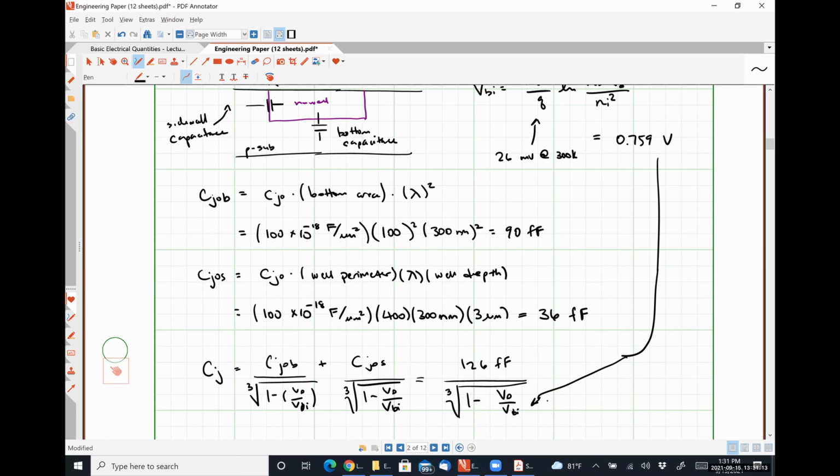However, when we use an N-well as a resistor, we're still forming a PN junction around the entire perimeter, or around the entire surface except for the top surface, which is ostensibly exposed to... we're looking at it like it's air right now, but it's going to wind up being silicon dioxide, forming a reverse biased PN junction, which looks like a capacitor. So we have in a single circuit element both resistance and capacitance.